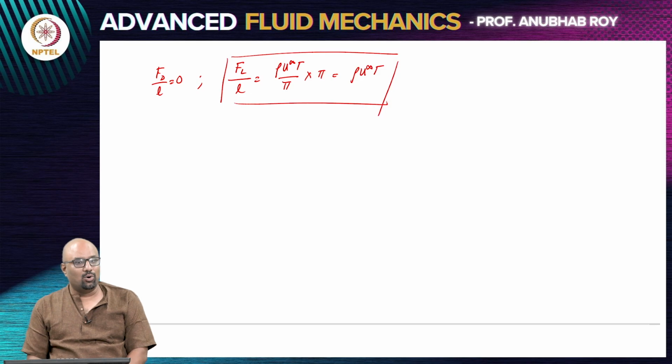So, if you have a flow over a cylinder with circulation, there is a lift force. So, this is an important result. So, even though the drag continues to be 0, and we will actually see this in a more formal manner, is this 0 because this is a circular cylinder? If it is irrotational, and if it was not a circular cylinder but an elliptical cylinder, if it was a square cylinder, if it was a cylinder which looked like the shape of the letter S, does it matter?